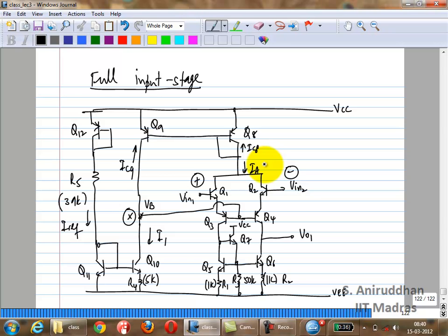Okay, so we have just taken everything except what have we added here. First of all, we have added this reference branch. Okay, what else? We have added the beta helper, and that's it. Actually, we have added this resistance here. What is this current source? We have seen this before, right? It's a Widlar current source. Remember this? You had it in one of the homeworks.